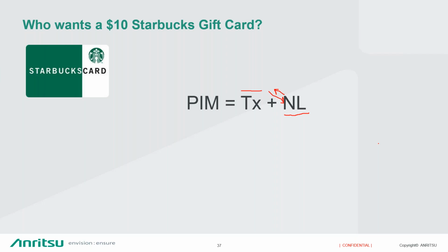Okay, and the last one I have here is, does a calibration PIM diode come with the IQ fiber master? Yes. At the end of the day, if you're familiar with RF, the PIM diode is a very strong PIM source, but you can use other strong PIM sources, like a ball of steel wool. But yes, the PIM diode does come with the IQ fiber master.